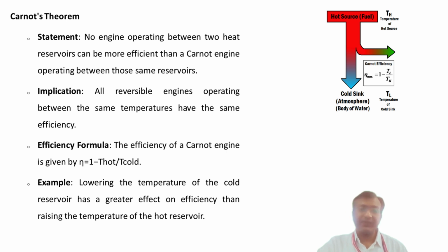However, there are practical limits to how much we can lower the cold reservoir temperature. For example, in a power plant, the cold reservoir is often the environment, like a river or the atmosphere, and so this cold reservoir temperature is fixed. On the other hand, Th, that is the hot reservoir temperature, can be increased by using a high temperature heat source. But there are material and economic constraints.